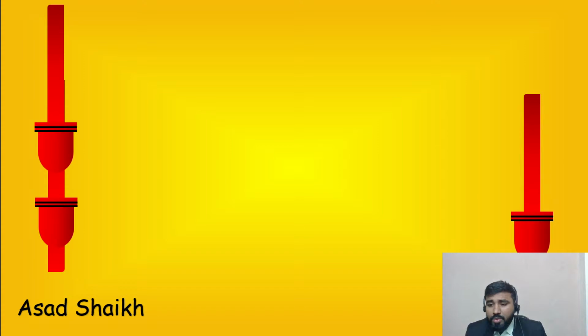If tight shutoff is not required, we can go for single port. But then what if your DP is very high and you go with single port? Okay, valve size will increase, makes sense. Response time to tackle DP rapidly, difficult to maintain. Okay, good point. Not experienced in engineering? Yeah, it's okay, no problem. I see a lot of amazing points here.